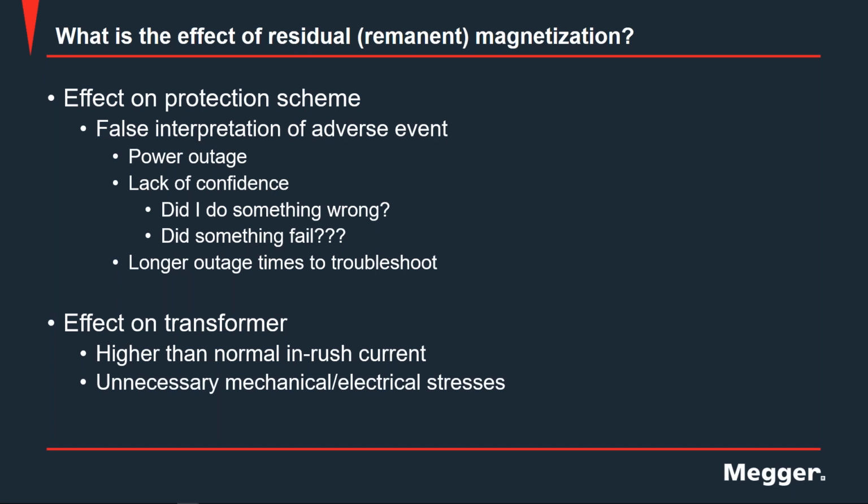And your transformer being one of the most expensive assets in your system, of course, you don't want to cause any unnecessary mechanical or electrical stresses. So making sure that your transformer is demagged and there is no residual or remnant magnetization is very important.